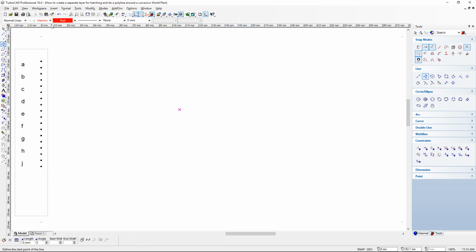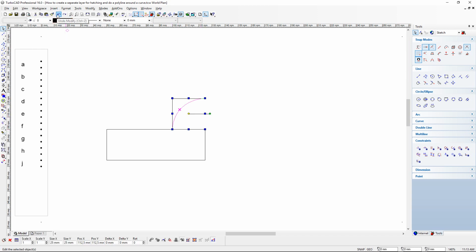Going back to the icon, and then I'm going to view my drawing there. Okay, now you see that in fact I have actually deleted the arc that was there, and the problem here was that I never selected the answers layer when I drew the arc. So all that I can do now is select undo, and it will bring back that arc of mine.